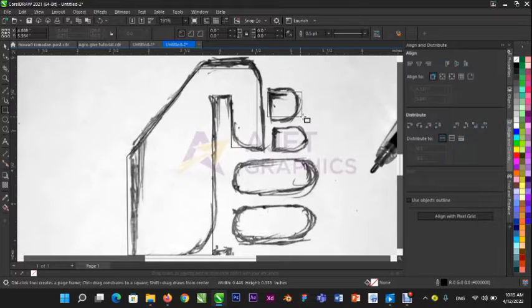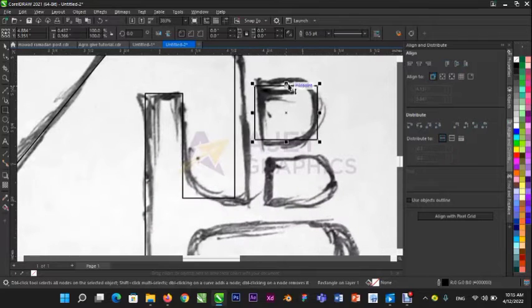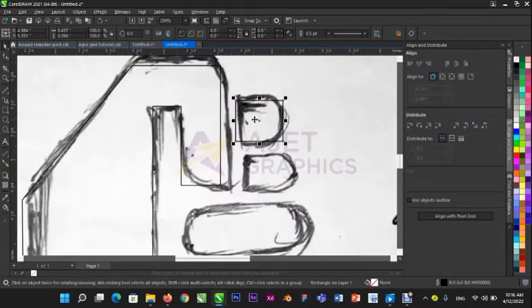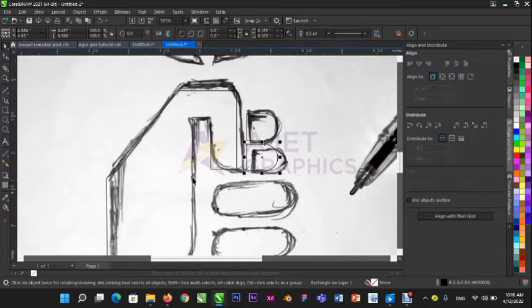When you select the rectangle tool, you draw the rectangle and make sure the size is appropriate to the sketch you drew. I duplicate it, then select the shape tool to curve the half part of the logo. As you can see, the rounded corner of the hand shows that it's a folded hand, so you select the shape tool to curve that aspect.